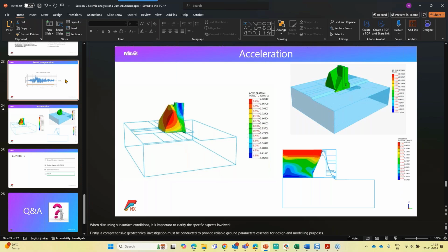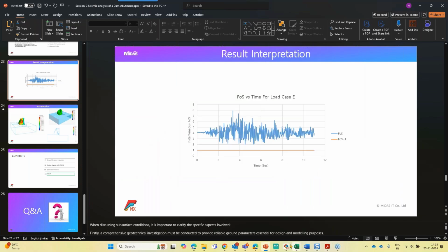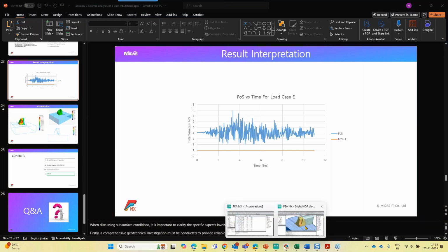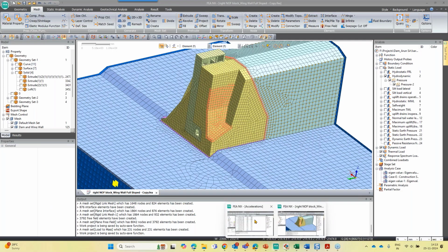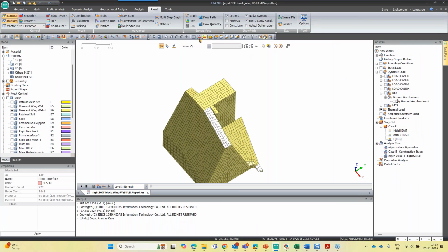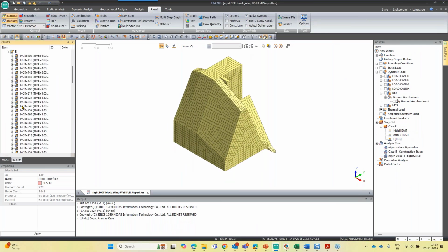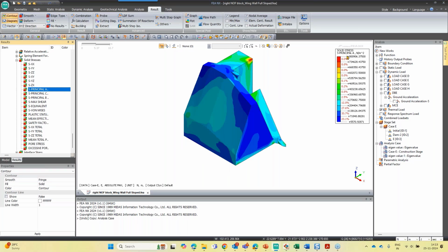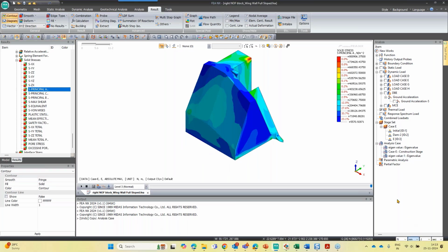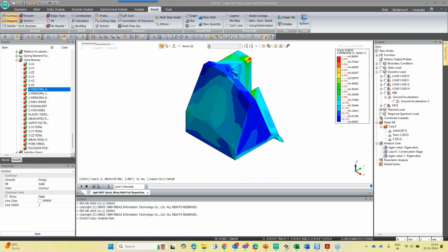The factor of safety has been satisfied, and even tensile forces have been satisfied. So tensile stresses. Let's see the tensile stresses in the model. Let's hide everything except the abutment. Let's go to the absolute force condition, and let's activate principal stresses. The principal stresses are the ones that will help you understand the tensile stresses in the dam. The positive value represents the tensile stresses, and the negative value represents the compressive stresses in the principal stresses.